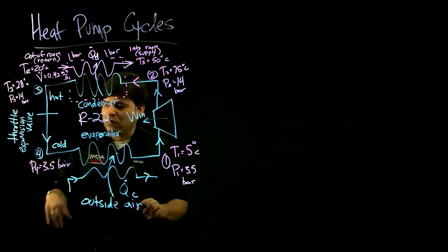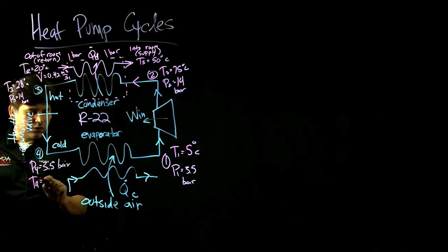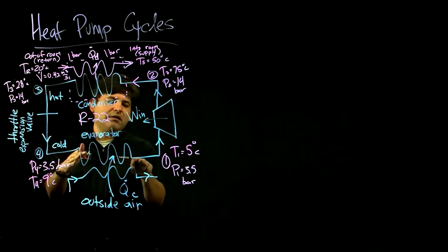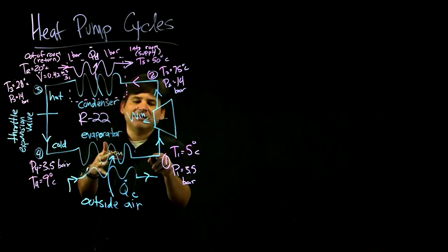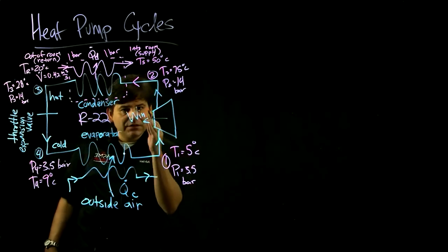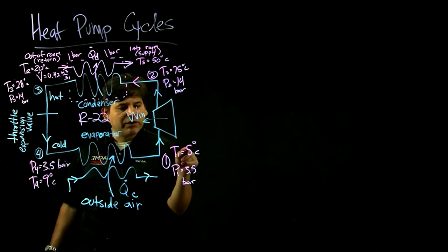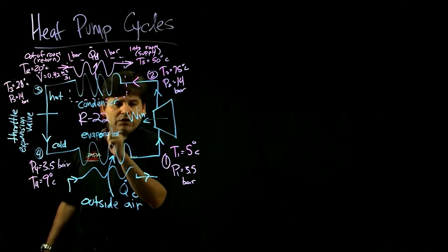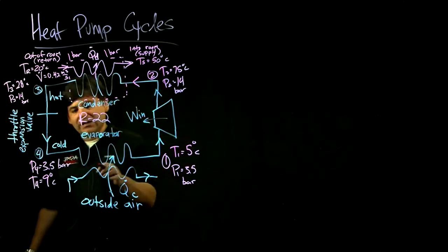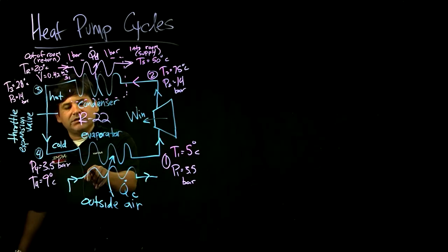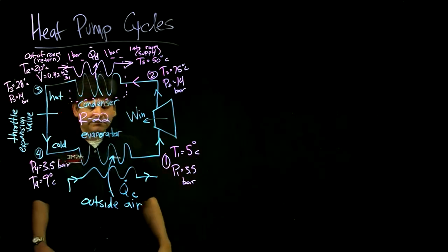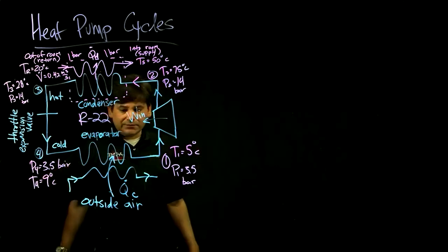So this is actually a little bit colder. This is T4 equals -9 Celsius. It's a little bit colder, but then when you evaporate, it's going to stay at -9 Celsius, but then we're going to go past the branch into the superheated state. So it starts off as a saturated mixture. We're going to verify that from the steam tables and the diagram. And it's going to end up as a superheated vapor, increase the temperature a little bit beyond this saturation condition.